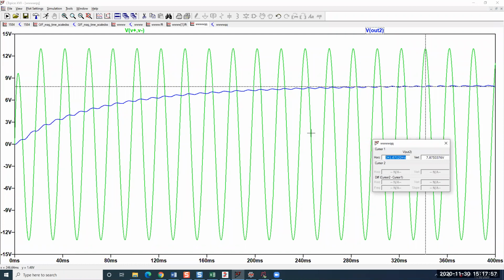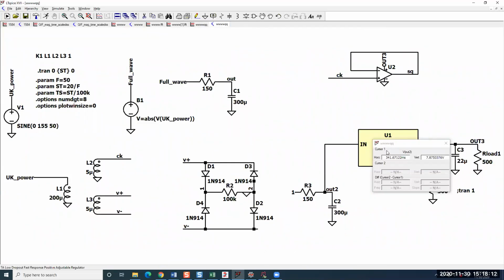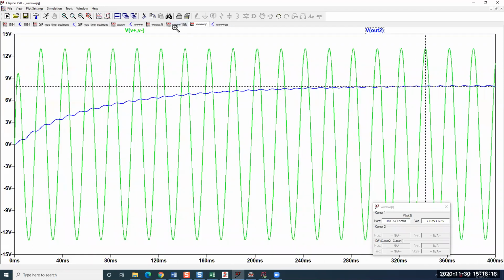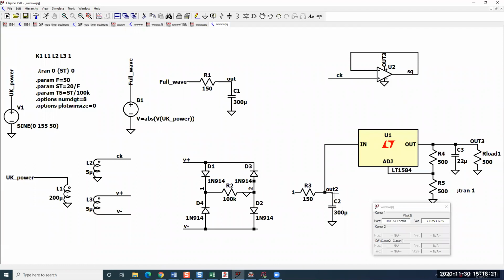The half wave rectifier, it's simpler, and it's also used though in demodulation. But yeah, it's simpler, but that's about all that it has going for it. So now this is DC with a ripple, but if I were to add a load resistance like 500, it would change the total time constant, and then there'd be this voltage division going on, and it would make it quite difficult to get a steady output voltage for any load.